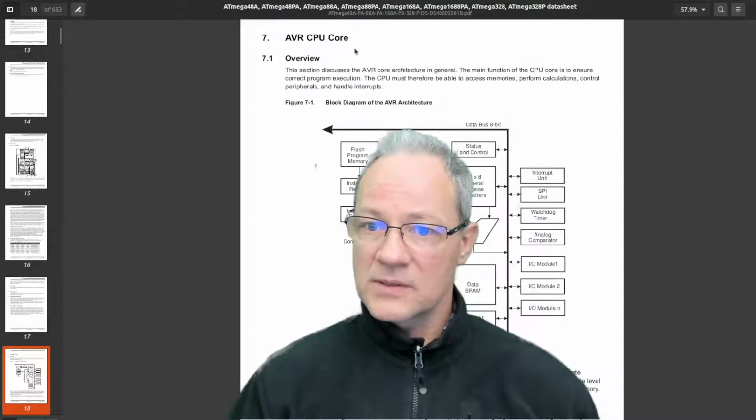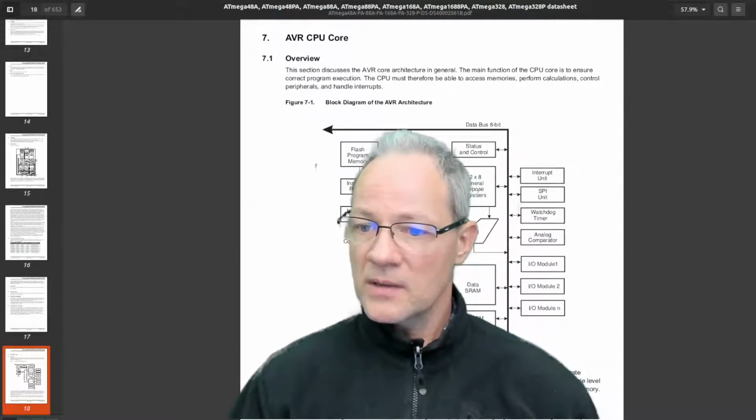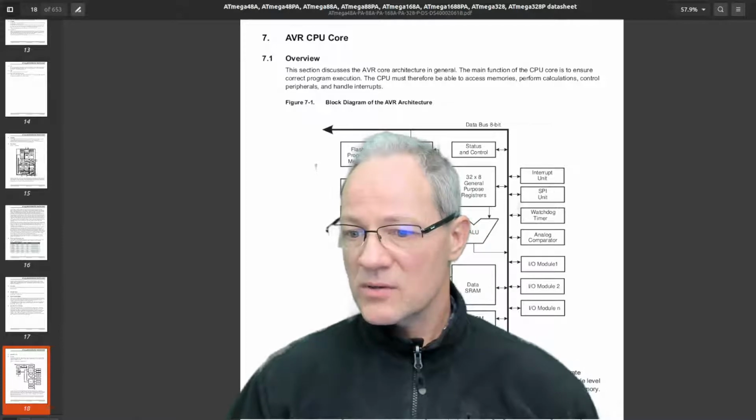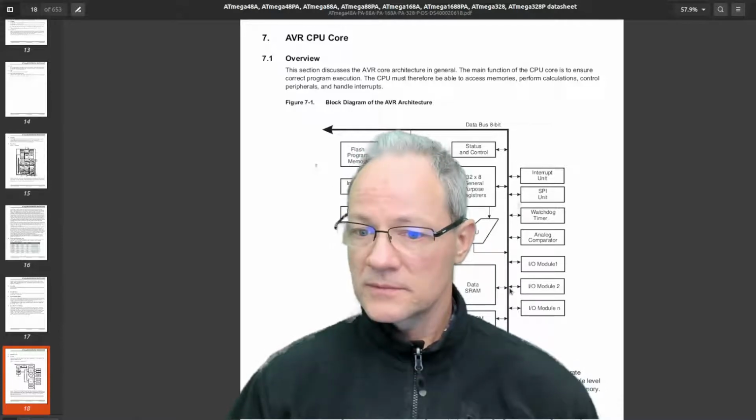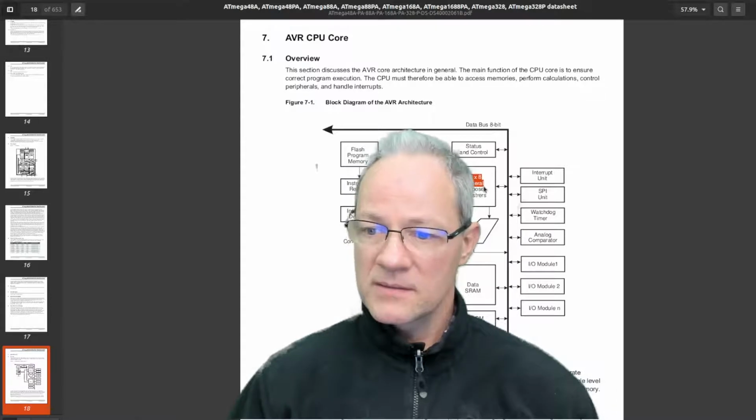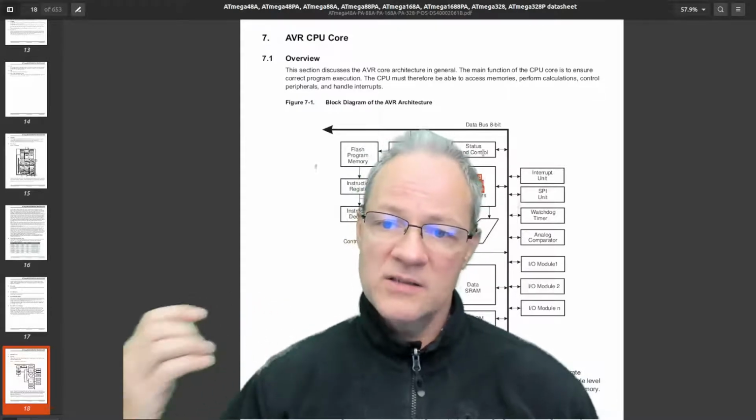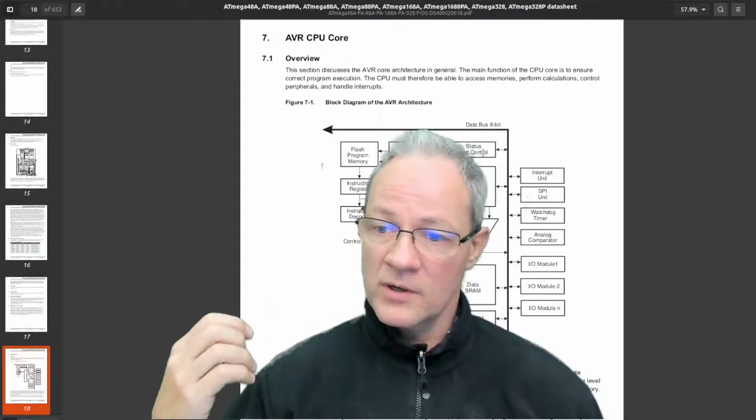Okay, so if we look at the processor itself, the way the processor is set up, it talks through the 8-bit data bus. So it turns out it's an 8-bit processor, right? And we can also see that from here, that it has 32 registers. Each register is 8 bits, right? So even the size of the registers is smaller than for typical processors.